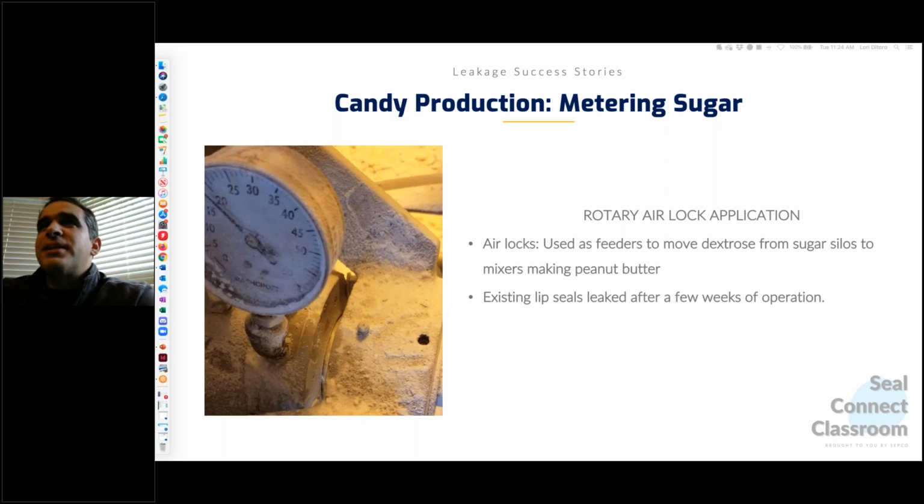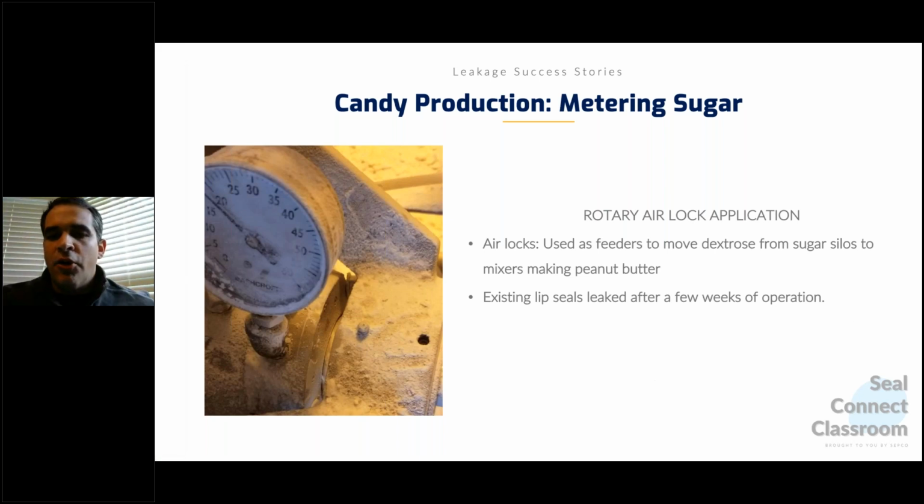Okay, yeah. So basically, a rotary airlock is an indexing, rotating application, and it indexes and delivers a certain amount of product to the next stage of the production, right? So if every batch of peanut butter needed, say, 12 ounces of sugar, I just made that up, that could be any number, the rotary airlock would deliver 12 ounces in the interval required to match the intervals that the peanut butter was being put in. So it's essentially an automated ingredient delivery system.